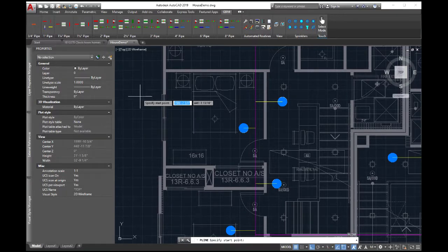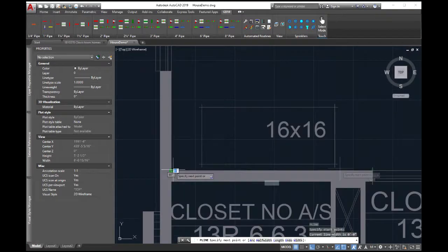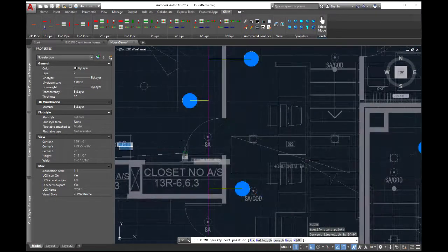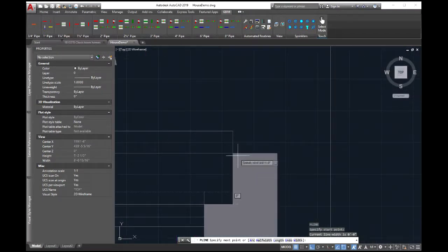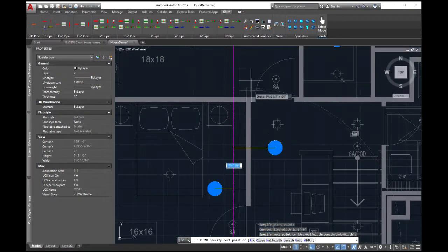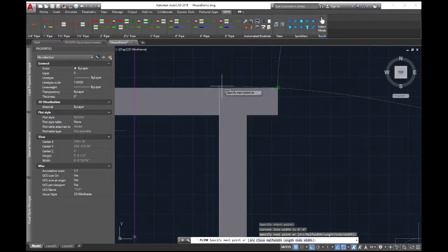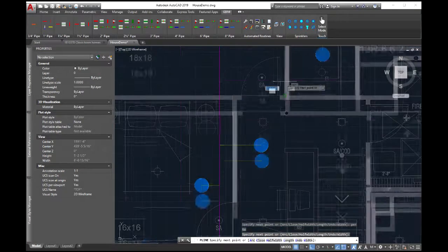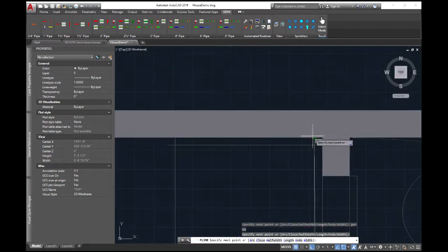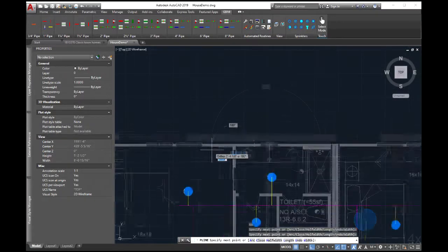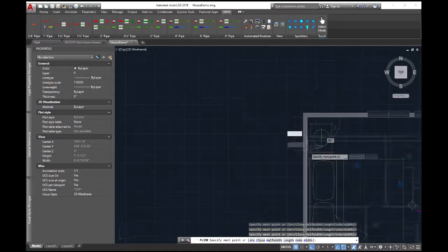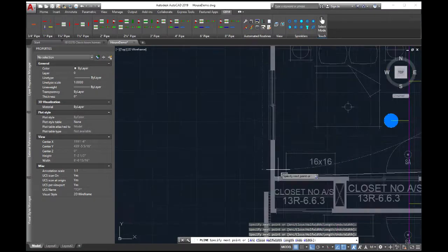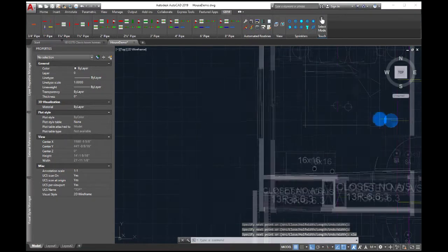So what we do is draw a polyline around them, and if you use the coverage, you can get some cool statistics to use. If you actually snap to what your spacing is going to be, I'm not going to get too accurate with this, but I want to give a good idea. This can be any form of polyline, you guys. I'm just going to surround my sprinklers with the two rooms that it's actually covering, and make sure that you close it. CLO, close. This has to be a closed polyline.